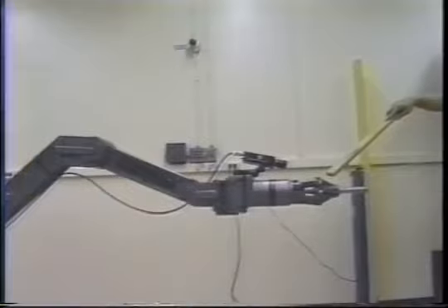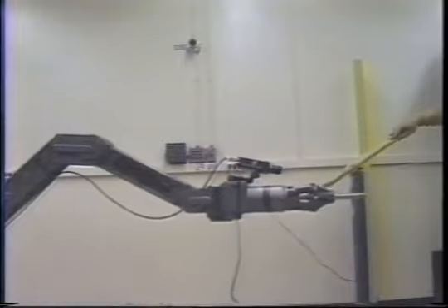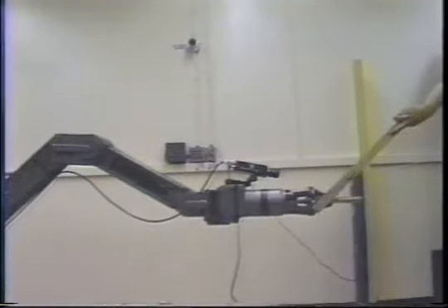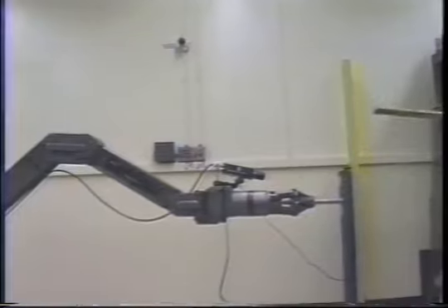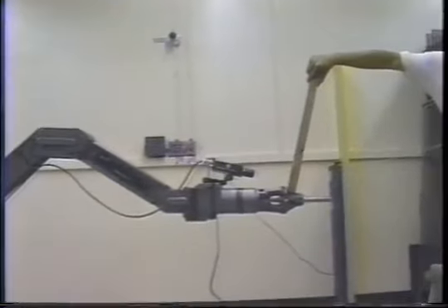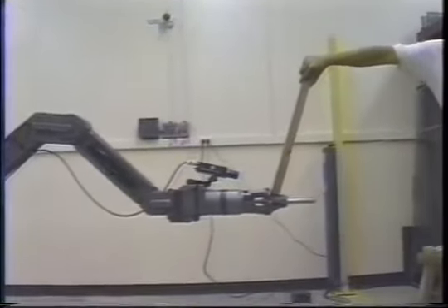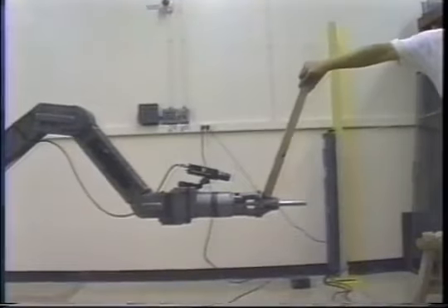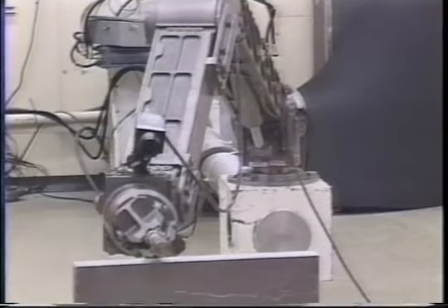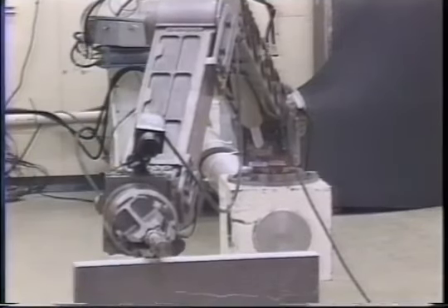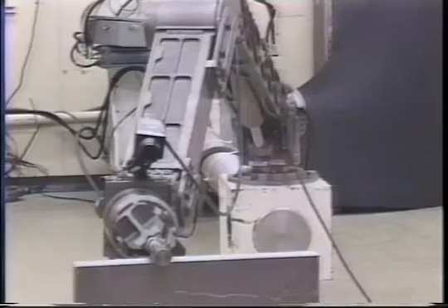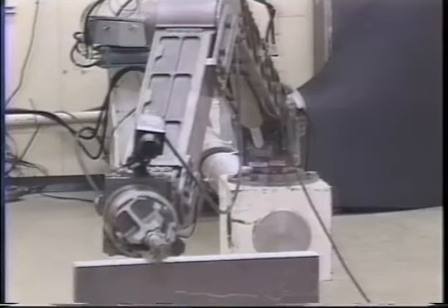In another example, a digital force-torque sensor was attached at the wrist of the micro-manipulator, and a force controller was implemented to the manipulator. As a force is applied to the sensor, the hydraulic manipulator moves accordingly. When a force-controlled manipulator makes a contact with a very rigid surface, it is well known that the contact instability occurs. The frequency of the limit cycle depends on the link compliance and force controller gains.